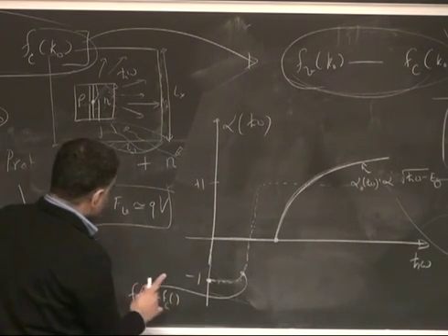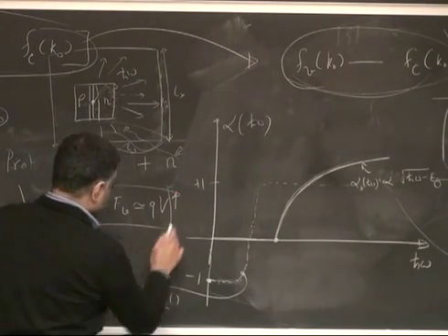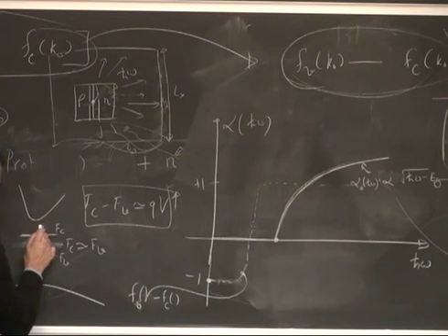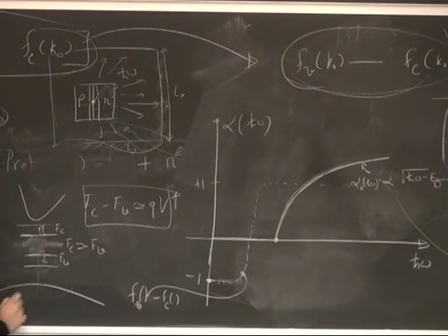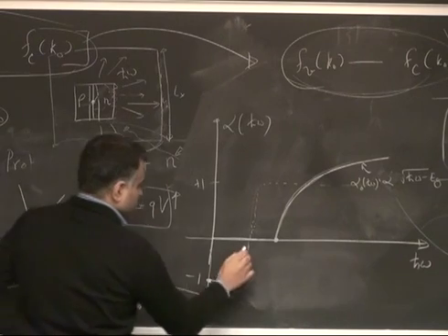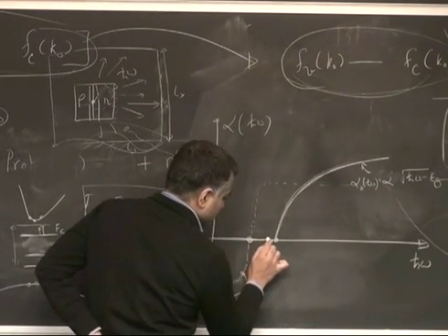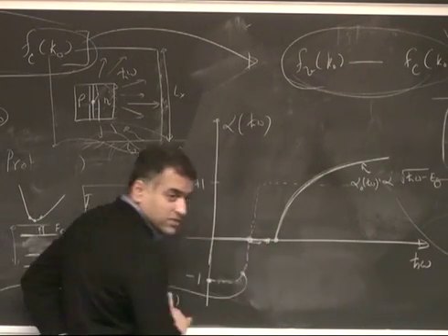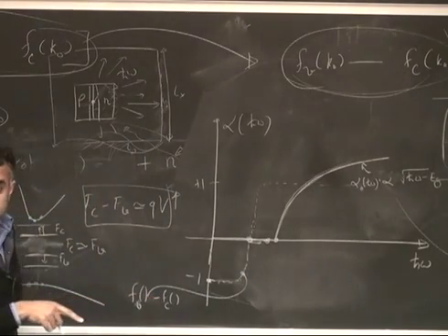What happens as you crank up the voltage? As you crank up the voltage, this moves even further here. It moves further down here. Increase the voltage, because the splitting is q times V, right? It increases. And so essentially you have more electrons now in the conduction band and more holes in the valence band. And the difference, Fc minus Fv, essentially what happens is this crossover point goes here. It starts shifting to the right as you inject more.